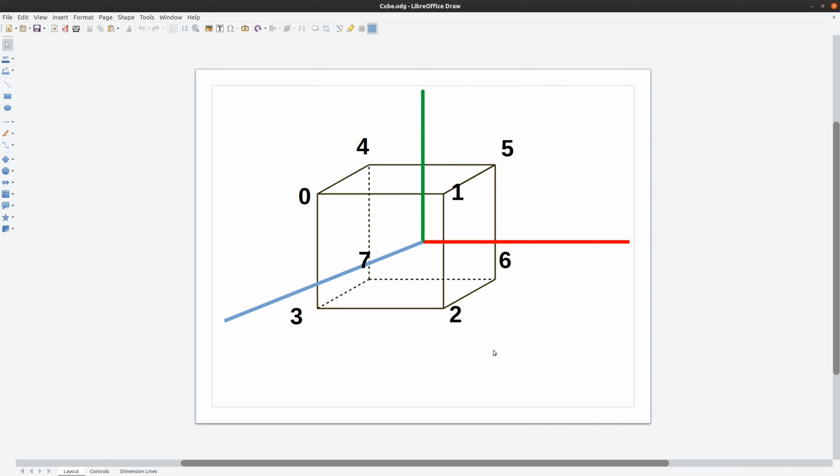So I'm hoping that makes sense because you have to kind of use your imagination here. So for instance here, you would do 1, 2, 6, which would be a counterclockwise. You wouldn't want that. You would want 1, 5, 6 for the top triangle here. You have to look at the face you're defining as if you turned it so it's facing you, so it's the front face. And then you have to make sure the vertices you're winding are wound in a clockwise winding as you're looking at it. And that can get tricky.